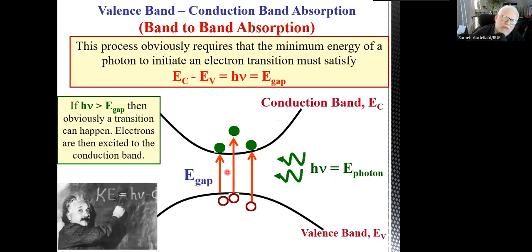This is a very important theoretical limit related to any solar cell ever: you will not be able to absorb all the photons across all the wavelengths in the spectrum. You have a very sharp theoretical limitation here. You can only absorb photons which have energy greater than or equal to the energy of the band gap.